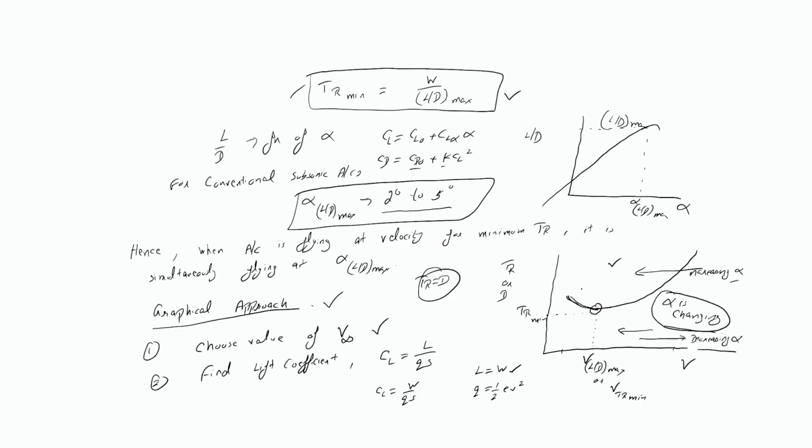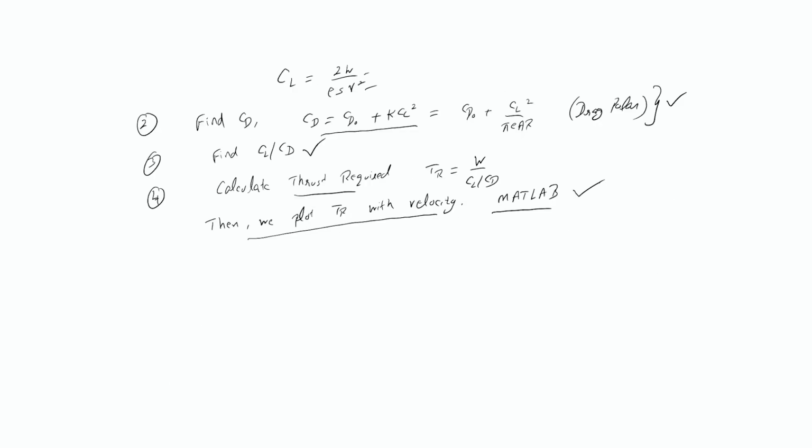So what is happening over here? That is the question that we need to address. Let me repeat here: as the velocity is reduced, the thrust requirement also reduces. It becomes minimum, but beyond a certain threshold, if velocity is reduced further, then the thrust requirement increases. So we are interested to know what is happening in this plot. Let us address this question.